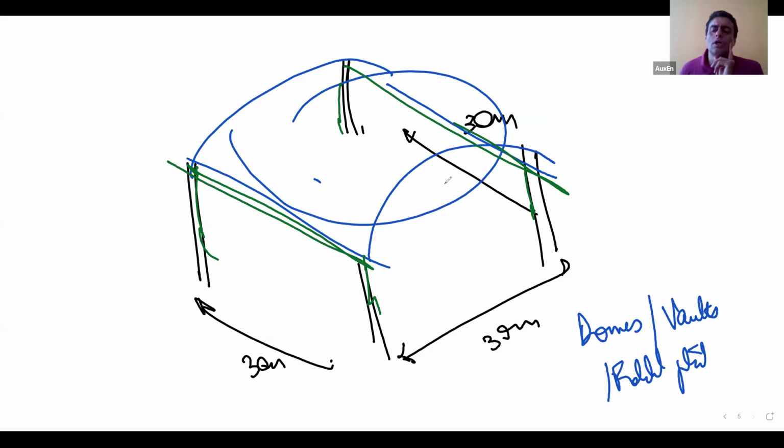And the same thing you can talk about in structural steel also. In structural steel for small spans, we may have single members or girders. For large spans, we may come up with trusses. For taking loads from two dimensions or taking area loads, we may come up with space frames, or we may come up with composite RCC concrete decks. So the systems may change in case of structural steel also. All right.